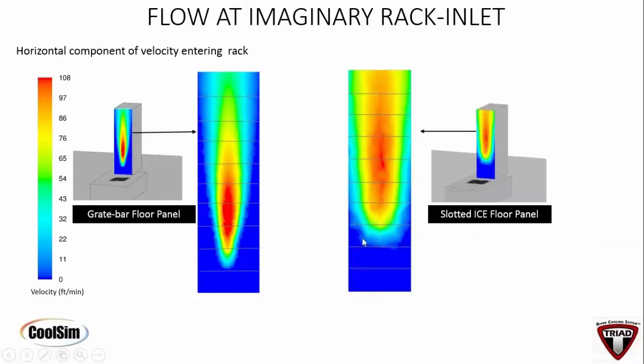The thing about a raised floor data center with cold air is the high density air always sits at the bottom. So although you don't have velocity pushing into the rack like you do from about a third of the way up, what you have at the bottom is a bunch of cold air. So I would think in this kind of configuration, it's fairly insensitive to location. What's your experience?